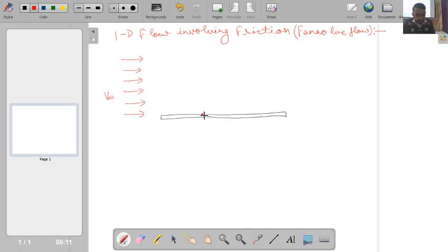will immediately get the velocity of the solid object. And as the solid object is stationary, this immediate vicinity fluid particle will also get zero velocity, and this is depicted as the no slip condition. And this particular layer tries to slow down its next immediate layer, because of which it will have some velocity but lesser than v infinity, and this keeps progressing, and finally we reach a situation where our velocity becomes identical to the free stream velocity.